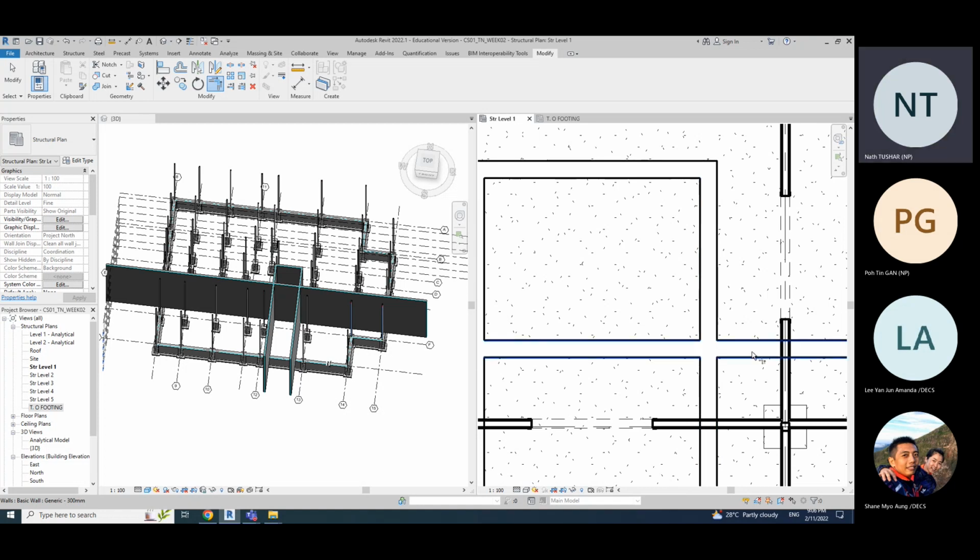So I am going to cut this wall, this extra wall over here and this extra wall over here. See my cursor? Are you able to see my cursor? I want to cut this wall from this side and I want to cut this wall from this side all the way. So I first select this wall and then I select internally this wall.